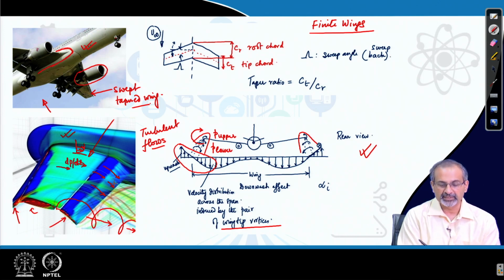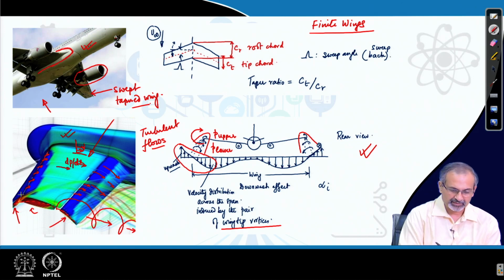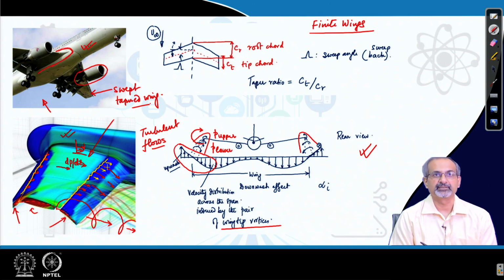So, of course, pressure gradient is handled more efficiently over here by making use of the momentum injection that is happening through the gaps which are created between the high lift devices and the main wing. But a turbulent boundary layer also enhances the robustness of the flow. So, these are the regions through which momentum augmentation is occurring in the boundary layer. This is one region, one gap, this is another one. Through this more momentum is getting into the boundary layer and energizing it.